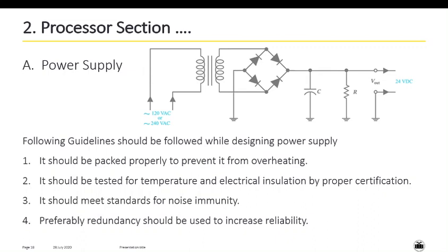Is it necessary to keep that power supply? No, but in case of failure of the current power supply, the parallel power supply can be immediately connected, and the failed power supply can be sent for maintenance. So that's why we keep this power supply, which is not in use, in parallel with the existing power supply. It is also called the redundant power supply. To increase the reliability of your production, we should preferably use a redundant power supply. So these are the guidelines for designing the power supply.